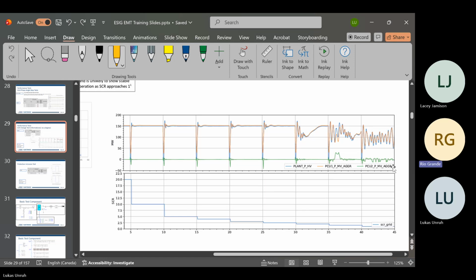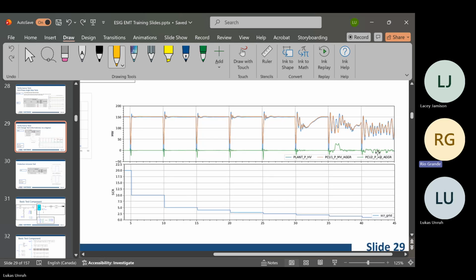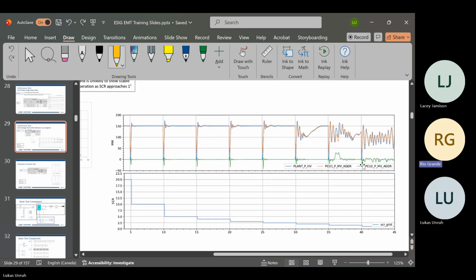And maybe you'll see very large overcurrents, let's say, that are maybe higher than what you would expect to see based on our understanding of current limits inside of IGBTs. Maybe you'll see it act totally flat, giving you extremely good performance.